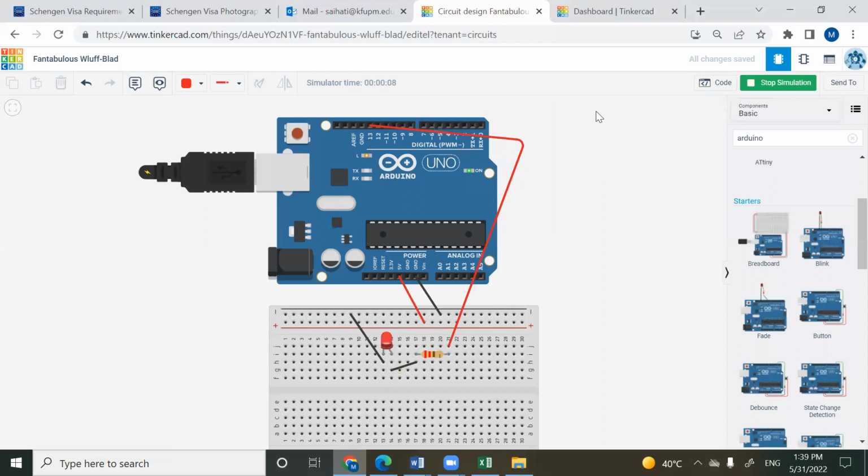Okay. Now, what I will do, just to make it simpler, I will have a switch as an input. Okay, a switch as an input, or let's say not a switch, I'll call it push button. Push button and LED. If this is pushed, if this is pressed, the LED will be on. If I'm removing my hand from the switch, this will be off. Okay. So clearly, I can use, for example, pin number 13 as an output.